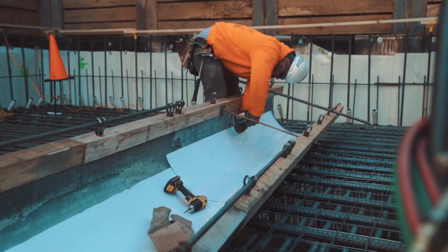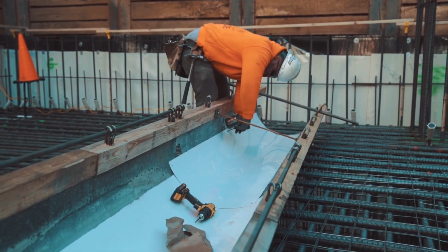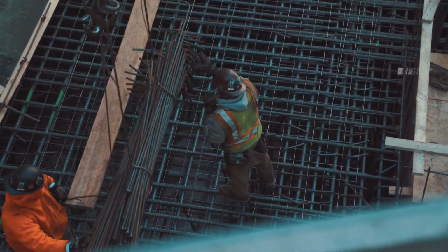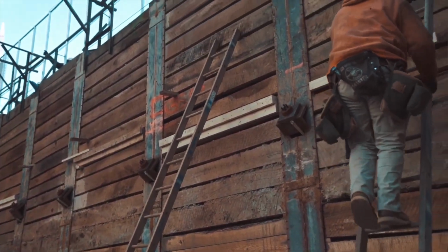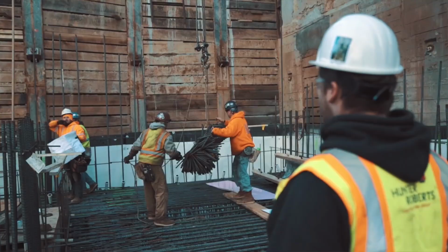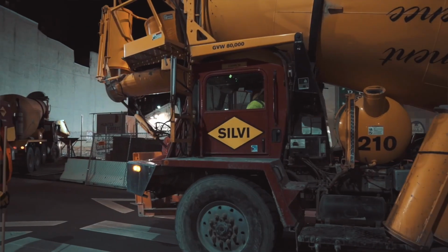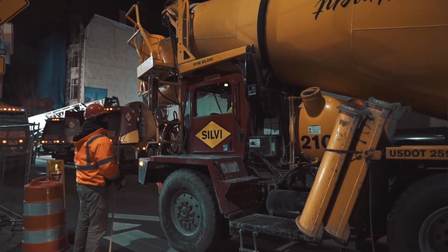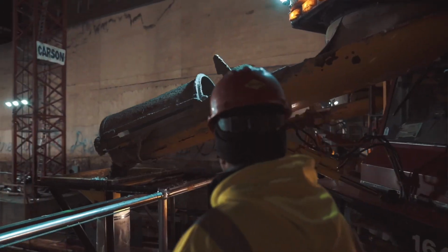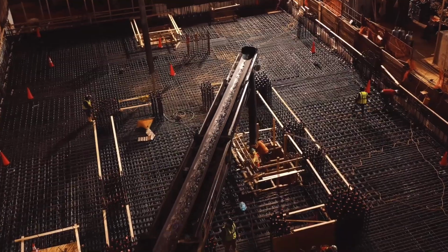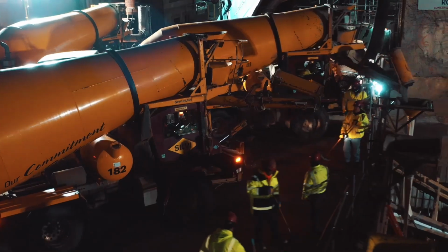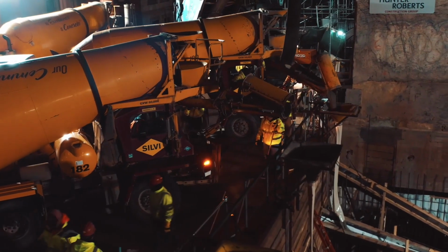The mat foundation plays a critical role in distributing structural loads over a wide area, minimizing differential settlements and resisting both vertical and lateral forces. The mega columns support the massive roof trusses above and transfer all upper loads directly into the foundation and ground. Through the use of high-strength materials, dense reinforcement, hydration heat management, and phased casting, this system successfully met the structural and construction challenges of the large-scale stadium.